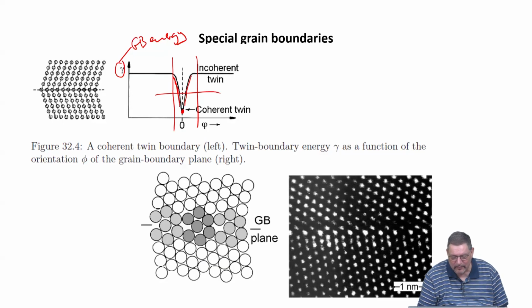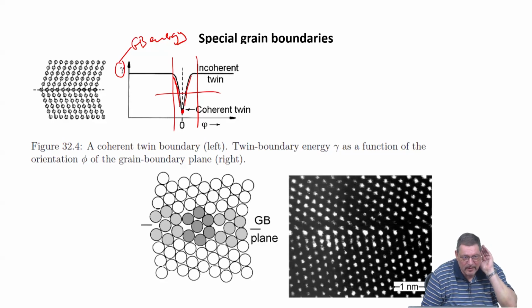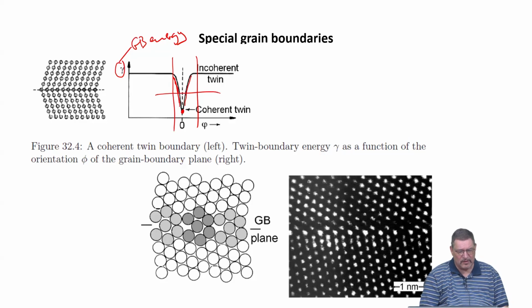Yeah, and if you anneal them, they tend to be getting more coherent, because annealing would serve to allow the material to find lower excess energy states, and this means it likes to form the twins, the coherent twins, if there are already twinned structures available. But it depends on the kinetics of the process, like how high is the temperature and how large are activation barriers for the jump, specifically in this already twinned structure. So it depends very much on the material, how long you would need to wait.